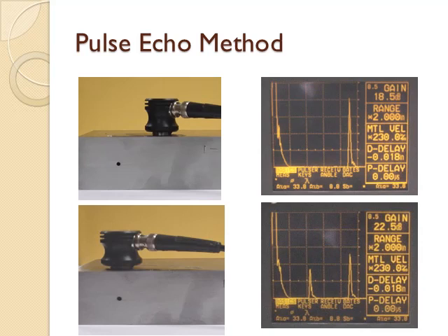These ultrasonic waves are transmitted through the specimen. They travel through the specimen and are reflected back by the other end. The reflected ultrasonics are received by the transducer and converted into electrical signals. These reflected signals are amplified and recorded in the CRO, and name it as pulse B.